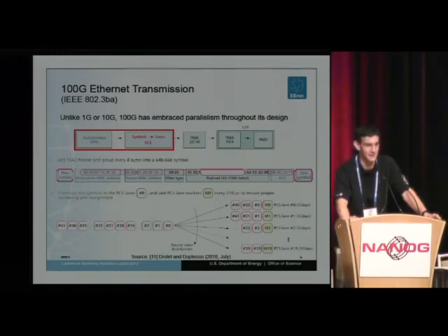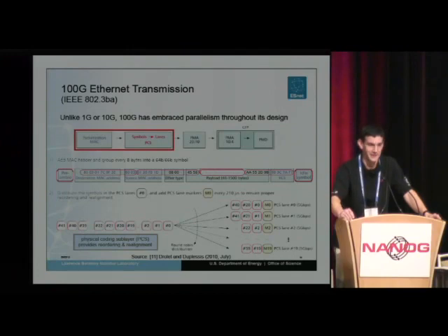They've really had to exploit parallelism throughout the design, and you see here the physical coding sublayer is really doing some SONET-like functions, providing the ability to avoid reordering and skew of the wavelengths. So it's adding very synchronous kinds of concepts to Ethernet to allow you to use 10 gigabit components and turn things into smaller and smaller signals and reorder them all when they come in